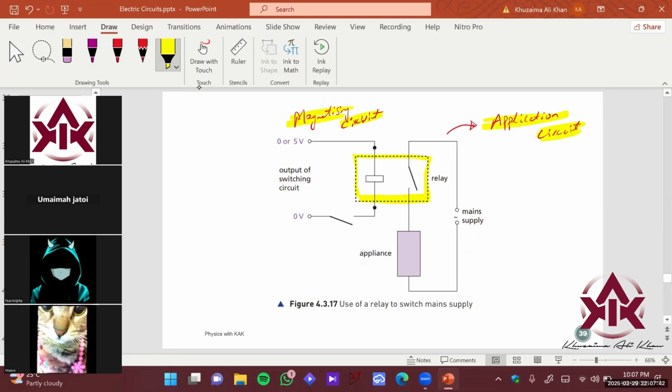Just like imagine a building, right? You want to power up the building over here, right? So what happens actually, we can close this switch here, right? Which is operating at only 5 volts, right? This appliance is working on 230 volts, right? So if you want to control an application which is operating at high power, you can create a relay which operates on very low power, right? For safety of your operation here, right?